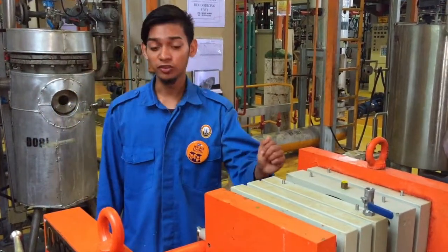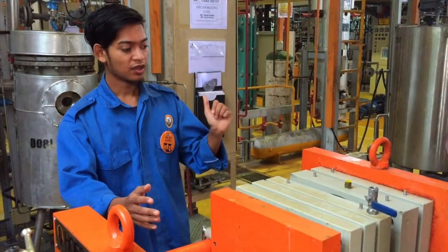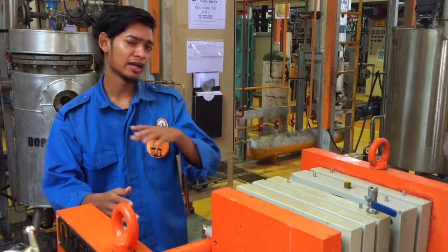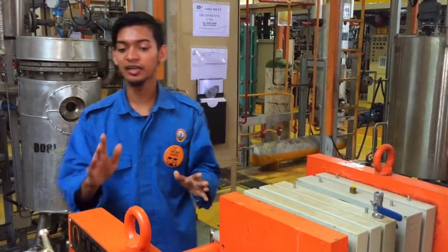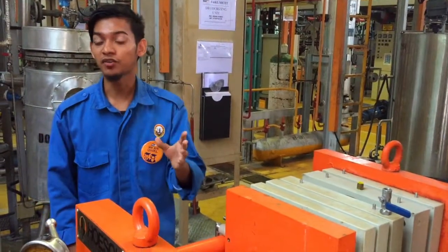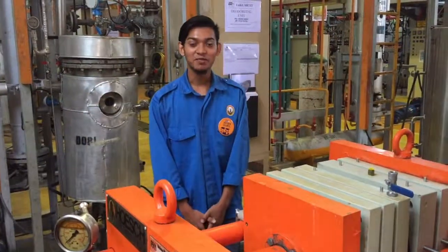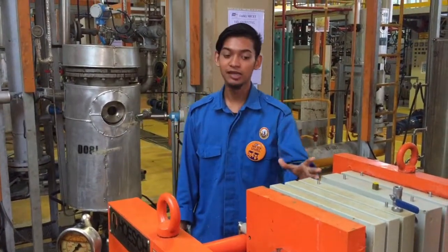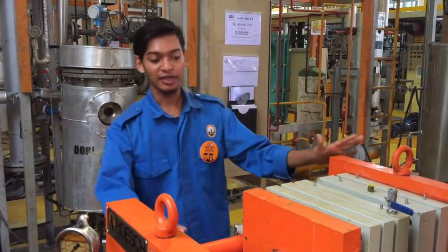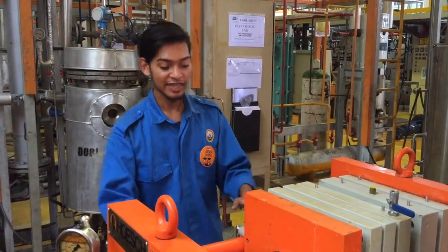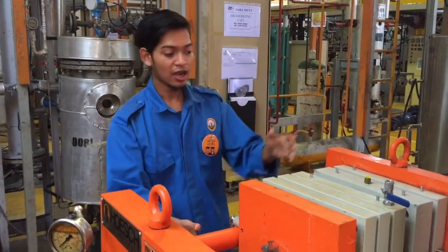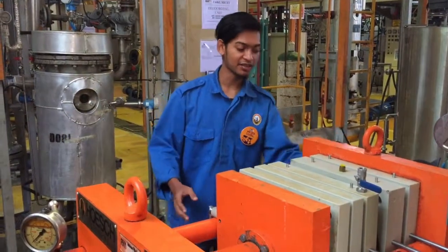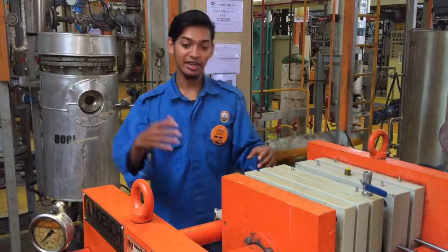Magnetic rubber is the most suitable as the filter press has a lot of small and unreachable places to detect cracks. Unlike the other testing methods, they can't reach the small and unreachable places. The improvement that can be done to improve the testing is by using magnetic rubber. Magnetic rubber can reach small and fine areas such as in the hole, in the diameter of this filter press hole, and other fine areas such as at the valve and others.